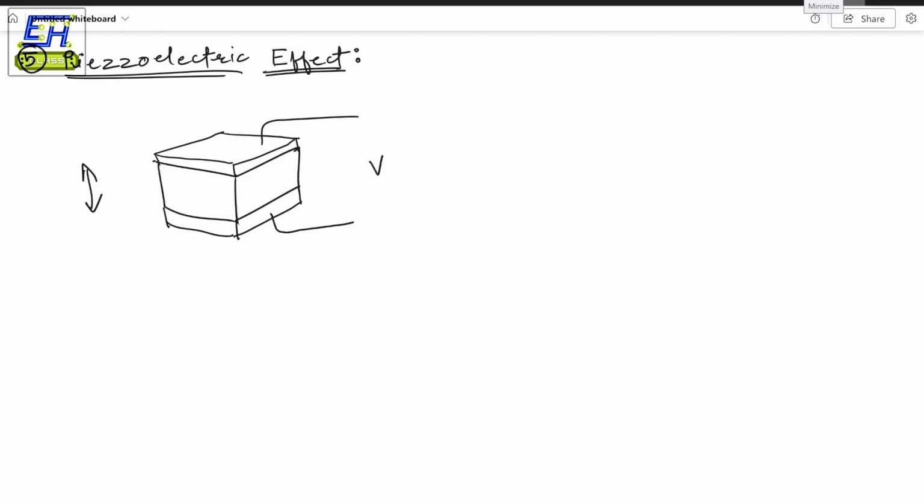But this voltage is obviously very small because the energy in vibration is not significant, but definitely you can use this as a source of energy when you have multiple cells in either series or parallel, similar to what we did in the thermocouple, or the thermoelectric generator. So this piezo voltage that is generated across the crystal is given by the piezoelectric charge constant, that is D, which basically tells us the sensitivity of the material to the applied force, right? How well it responds to a certain amount of force, multiplied by T, that is thickness, divided by the permittivity of the material.